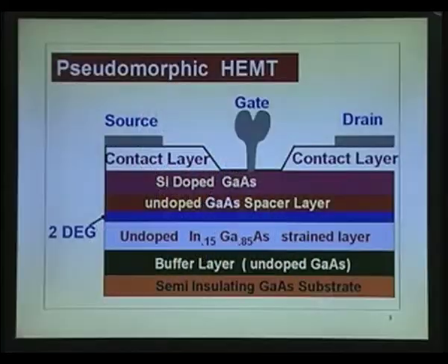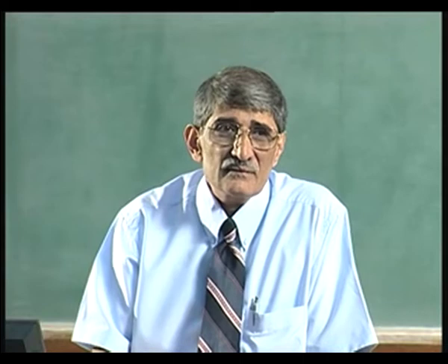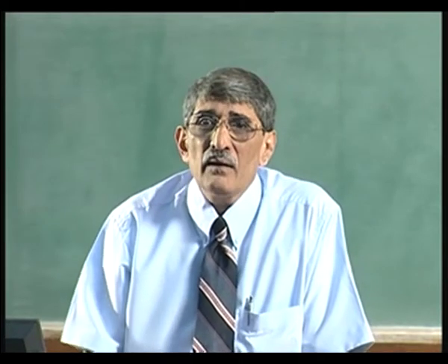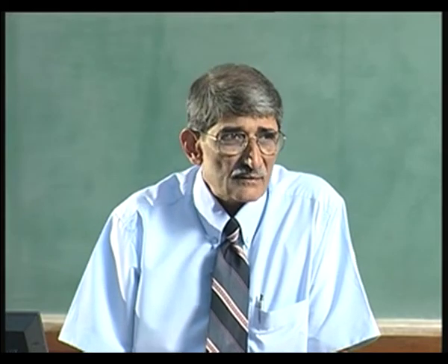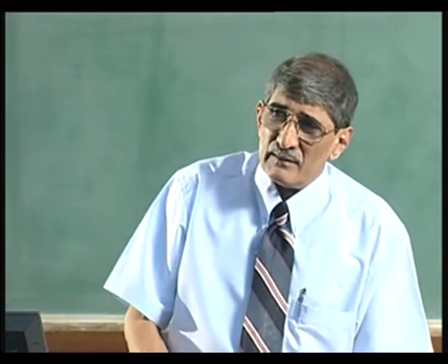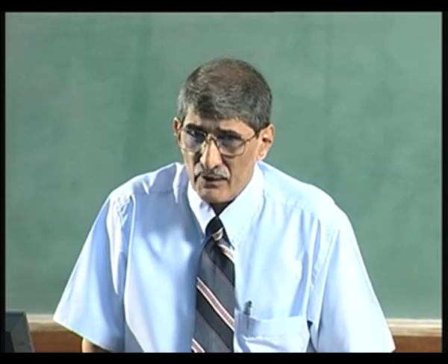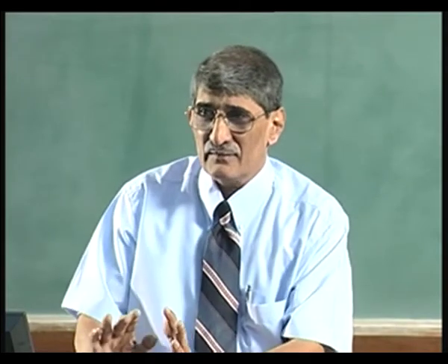Okay, now let us just take a look, so that almost right now we close the chapter on field effect transistors, with which we have discussed MESFET or JFET or both, same performance. Instead of Schottky barrier you put a junction, it becomes JFET, and then high electron mobility transistors with gallium arsenide based, indium phosphide based. All these you can classify as FET.